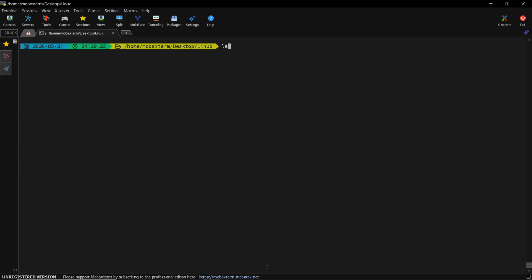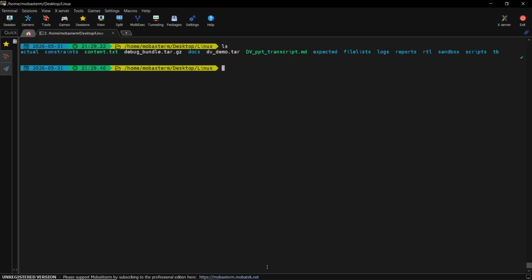So this is my last module of this video. This is a mini debug workflow. First, what is a debug workflow? A debug workflow is a step-by-step method to understand why something failed. In DV, a typical debug workflow starts from a failing regression or simulation log, then searches error messages, checks source references, compares expected and actual output, reviews coverage or reports, and finally collects useful files for sharing.